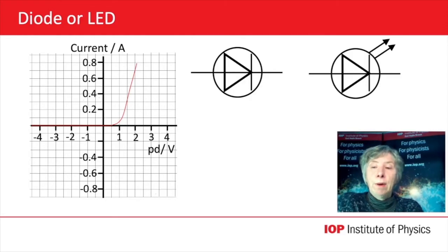In forward bias, i.e. when a positive potential difference is applied across the diode, it will start to conduct at a very specific potential difference, for example 0.7 volts. The resistance will become very low and the diode conducts. The interesting part of the graph is when this actually happens. We say that the diode has switched on, and the student may like to go back and take more readings around this value to determine the shape of that curvature as the diode turns on.